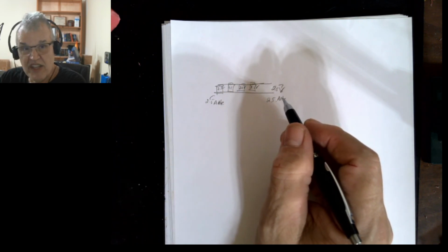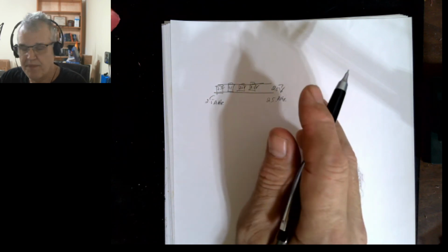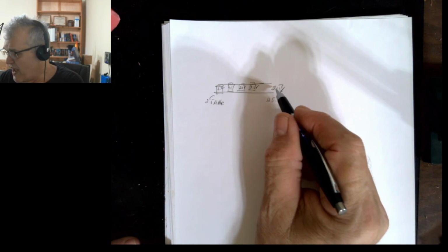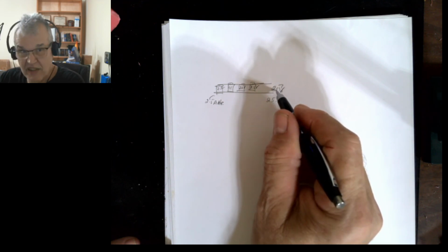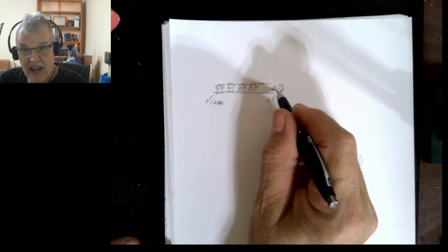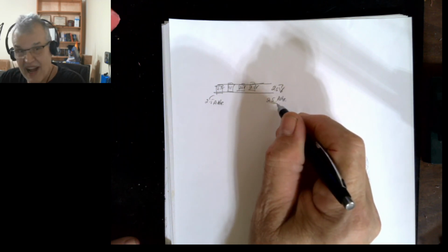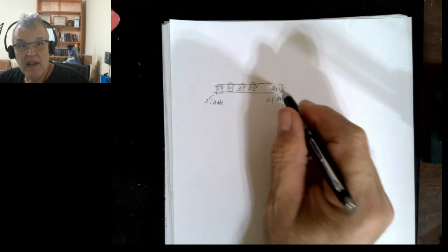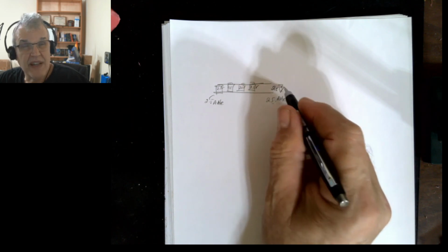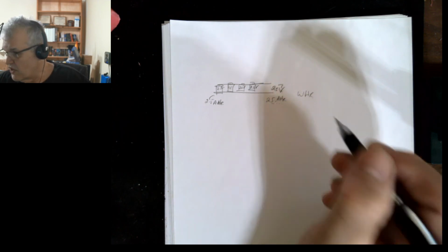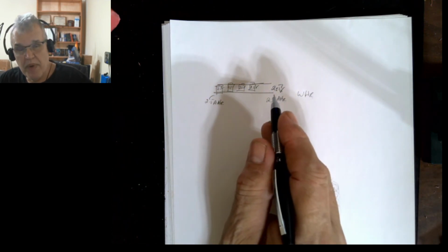And then you can see that the energy of the system increases, energy being watt hours. Remember, watts is volts times amps. My amp hours is 25 now, at 2.5 volts. So 2.5 times 25 is 62 and a half watt hours. So you can see how that increased. That's if you do them in parallel.